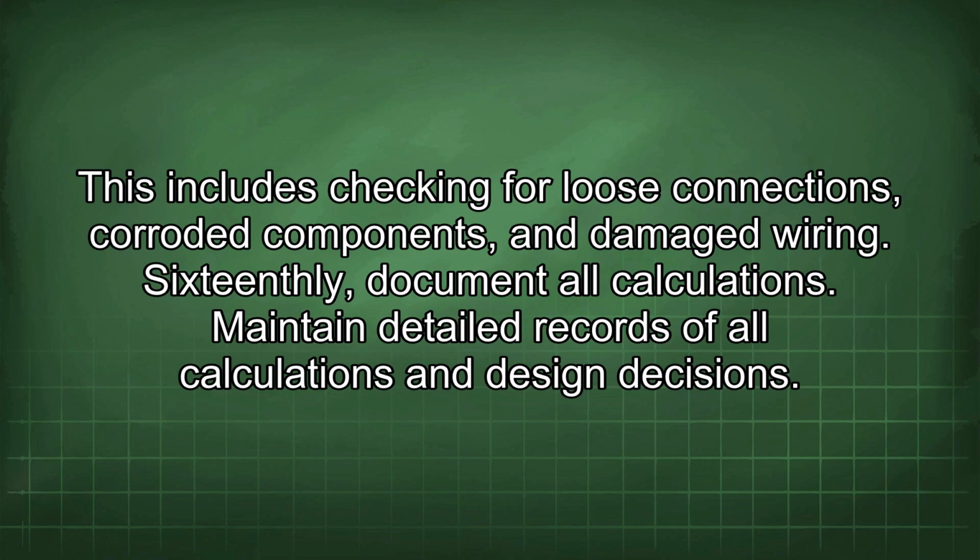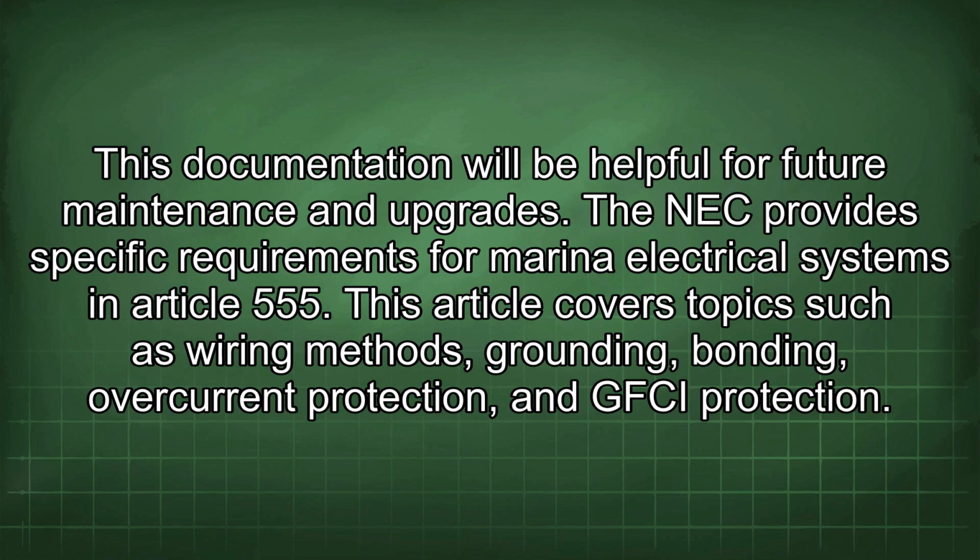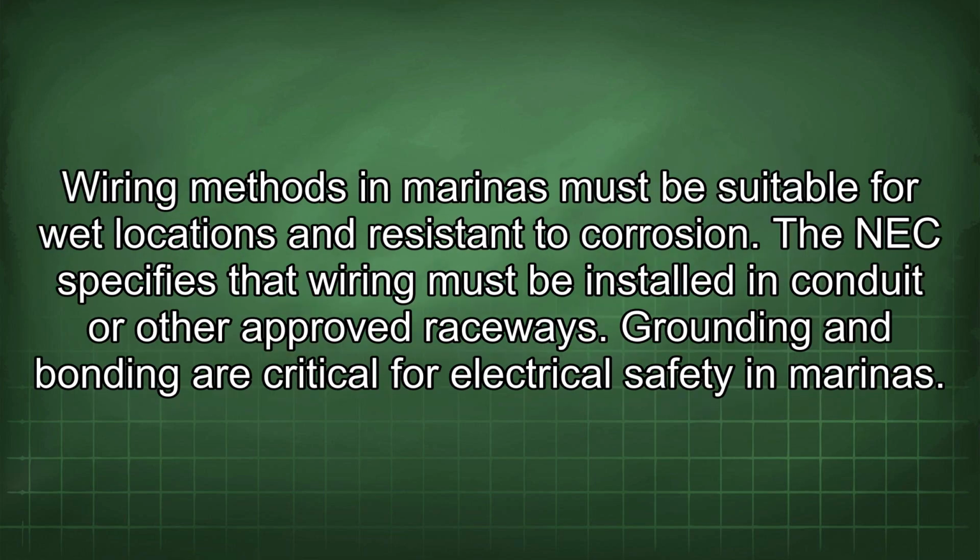16thly, document all calculations. Maintain detailed records of all calculations and design decisions. This documentation will be helpful for future maintenance and upgrades. The NEC provides specific requirements for marine electrical systems in Article 555. This article covers topics such as wiring methods, grounding, bonding, overcurrent protection, and GFCI protection. Wiring methods in marinas must be suitable for wet locations and resistant to corrosion. The NEC specifies that wiring must be installed in conduit or other approved raceways.